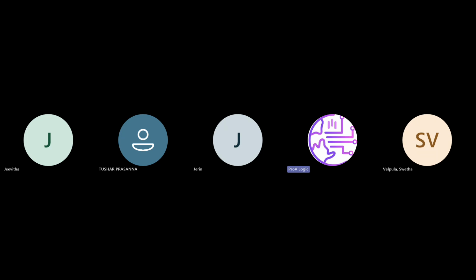Next, what is meant by sensitivity list in Verilog? They are the values used in the always condition that execute the always statements. Based on the variables changing in the sensitivity list, the always block is executed. Okay, fine.